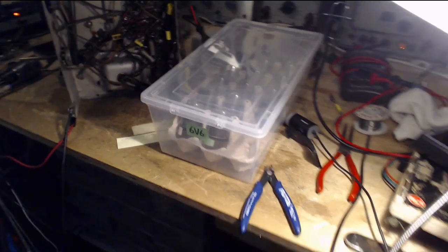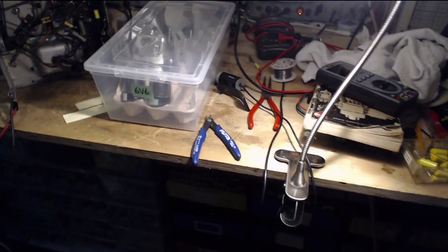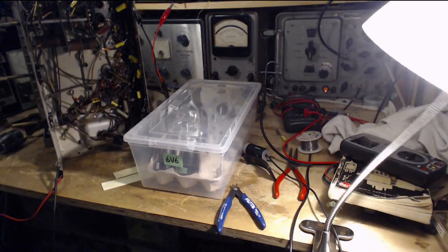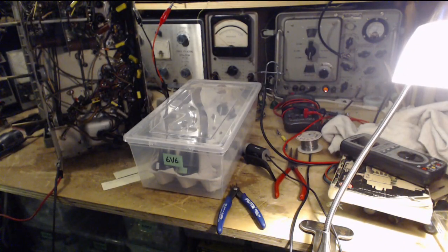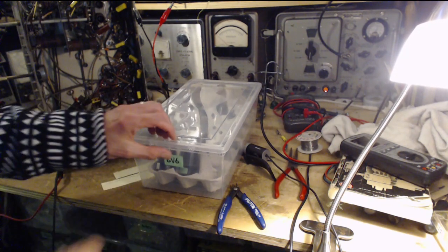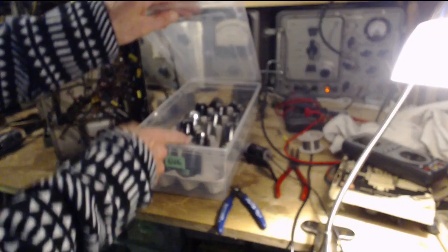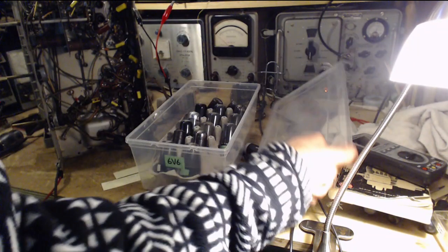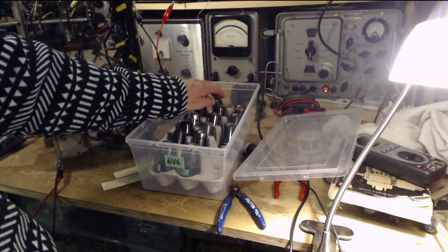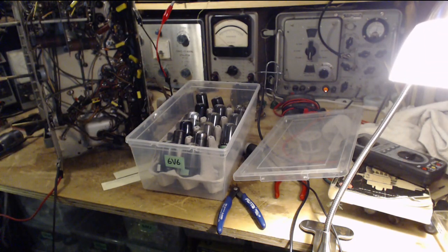Okay, so I read a little more about what people say about using 6V6 tubes, and I think it's worth trying. It should work. This is a push-pull radio. The biasing is probably okay, but we can always check it and see what it actually is. If this tube gets biased too high, if it's too much of a negative bias on the grid, all that happens is the tube won't be as strong in its operation, and it may get driven into cutoff.